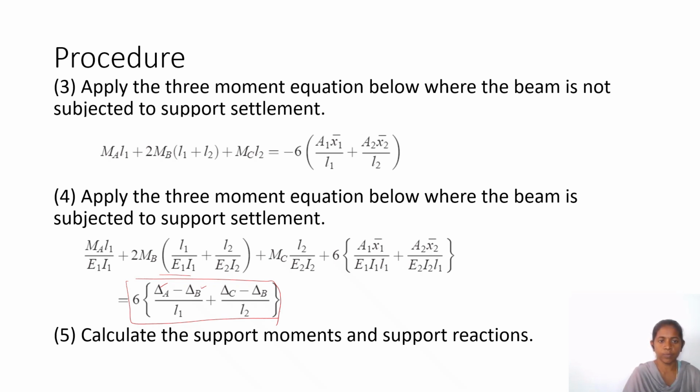Finally, you solve the simultaneous equations formed by the theorem of three moments, and calculate the support moments, and you can further draw the bending moment diagram. So this is the procedure for Clapeyron's three moments equation. You have to be familiar with this method, and you can practice many problems. It is very easy to attempt in the examination also.